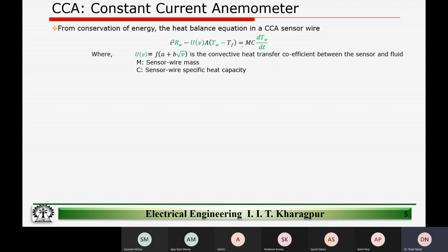And how much will the temperature increase? Of course, it depends on the mass, right? The wire is going to heat up more and more if the mass is higher or lower? Think just from a normal thing. If the delta energy remains the same and the mass increases, what will happen to delta dT? It will reduce, right? Because mass comes in.